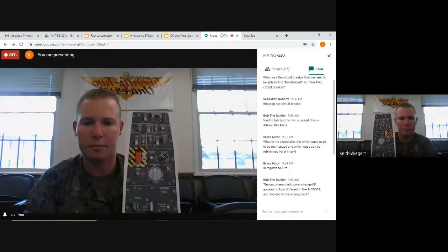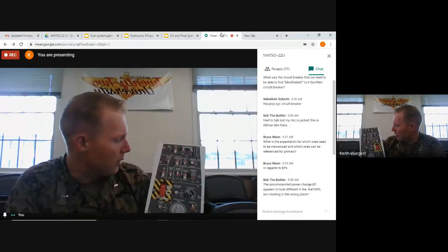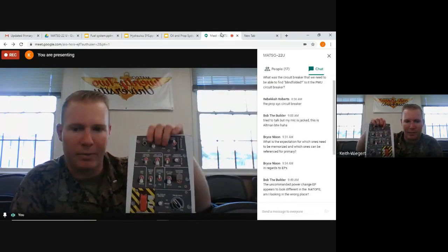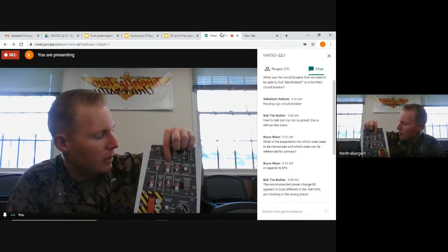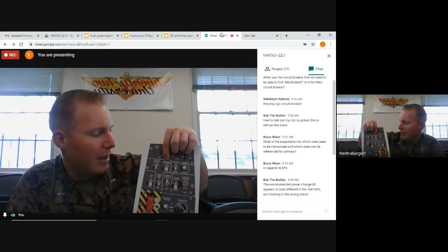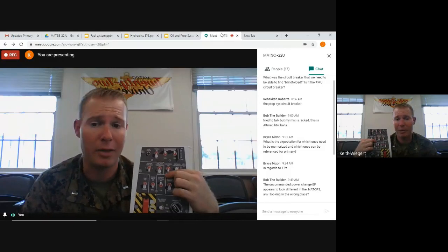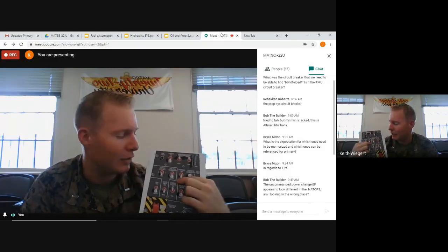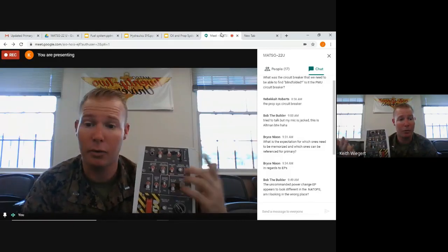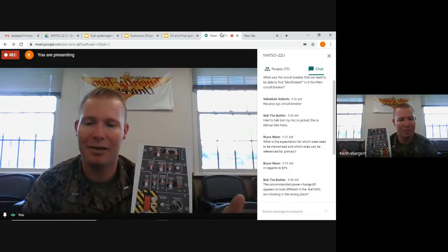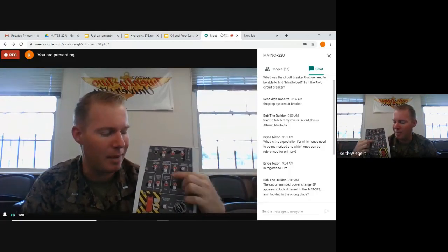So we've got our fuel balance switches up here, right? So we've got our fuel balance switch. It's got two positions. It's got manual reset and it's got auto. Most of the time, you're going to fly around with it in automatic. That's going to be automatically balancing your fuel and keeping them within limits. The computers are doing that. We'll talk about that in just a second, right? Most of the time, that's going to happen.